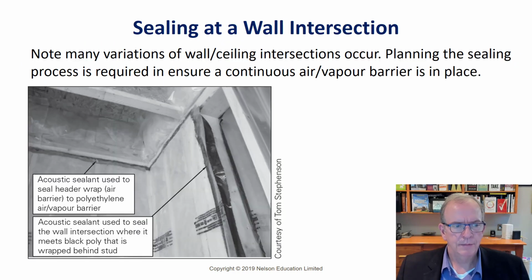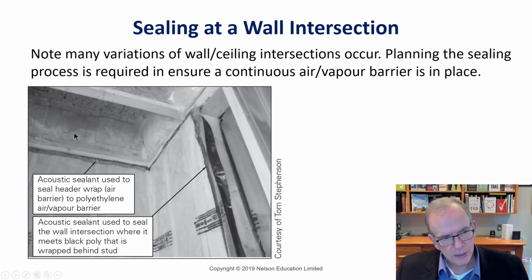It kind of follows that process. And again, you can see here, and this is stopping, I think, in this part over here, it's not outside, but this section here, the house is an outside wall. So the outside wall stops here somewhere, and then your inside wall. So that's why you don't see it. You also see the batt insulation tucked in along the top here, and then this gets sealed here. Because the other thing is, the reason you put a header wrap is you'd never be able to tightly seal in between all of these.